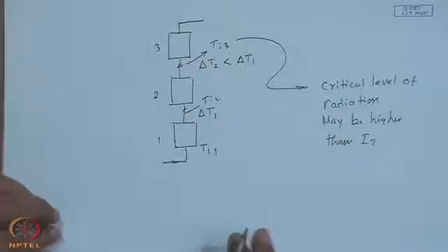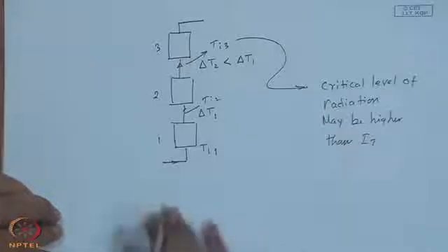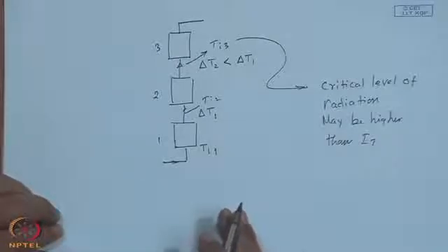In other words, a stage will come where the last of the collectors may not be able to provide further heating to the fluid that they receive. So, this is one danger one has to reckon with when the collectors are in series compared to parallel mode. So, one can think of a combination of these things.